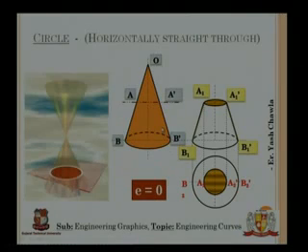This is a cone which I am seeing from the front, and then this A' is the plane, this red plane. I have visualized it with a single line. I am just seeing it from this end instead of seeing it in isometric view. So I'll remove the top part because I have cut it. So I'll remove this part A' and O. I have named it A1 and A1'. This thing that is the result, if I view it from the top, will be something like this, which is the circle, with A2 and A2' as the diameter, and the outer circle is the base circle of the cone. So I have the resultant circle, for which E is equal to 0.